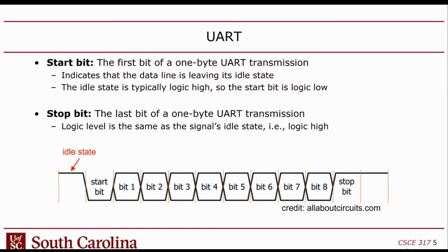And then you send the bits serially. Now, what order do you send them in? Well, that also depends on the implementation. That's something else the sender and receiver have to agree on. So you might send them from most significant to least significant, or from least significant to most significant. But you send a series of bits across the channel, 1 bit at a time, and then you hope the receiver can reconstruct those bits into a word with the proper bit ordering. And then when you're done, you may have a stop bit, which is when you hold the channel high for one bit time.